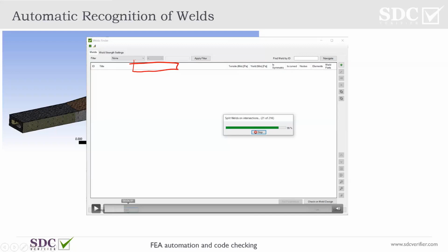Well, actually, not really. The initial calculations at the design stage are something else, because at the end they give you the service lifetime for your crane, the lifespan, right? So this is an indication that your crane design is good enough for a certain number of years. However, with this approach, we do it the other way around. We are recalculating your crane with the real situation, because very often at the initial stage these design assumptions were very conservative, right?